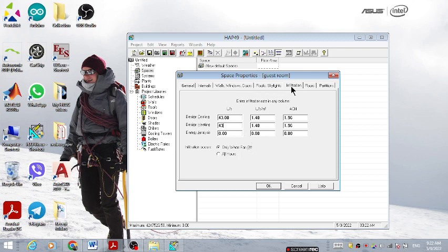Okay, this is infiltration. Do we need to consider ventilation or not? I'm not going to explain it here because we don't have time. But this infiltration is not under control. This is air infiltration from cracks of windows, doors, and opening and closing doors as people enter and go out. So we assume that the air inside the space is replaced 2 times each hour. From that, we calculated the rate of air infiltrated. We have 15 people times about 3 liters per second each, so we need about 45 liters per second. I think the infiltration rate is enough for people to maintain fresh air inside the space.